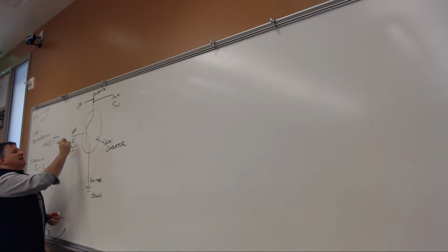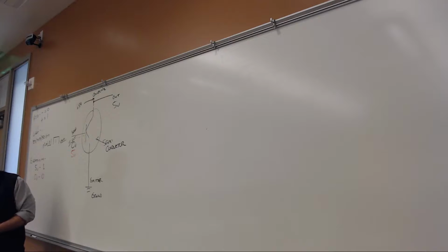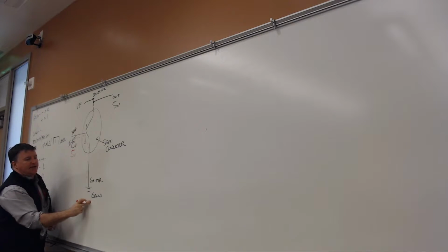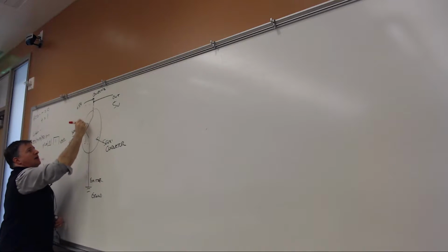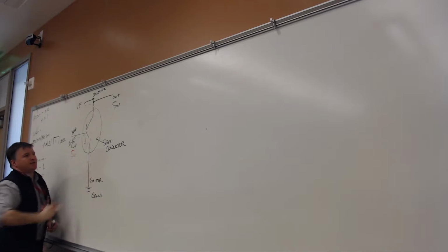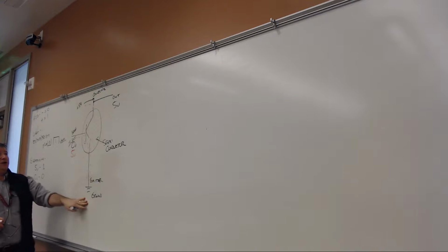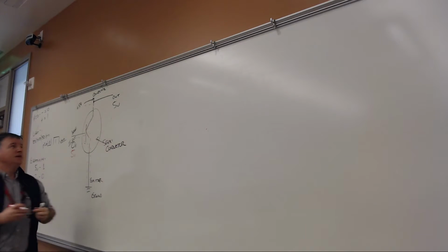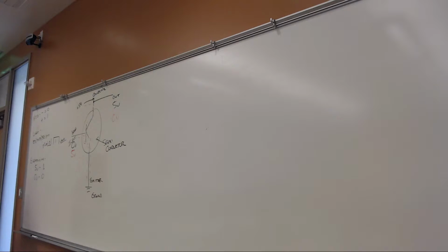And when it becomes a conductor, all 5 volts that I put in here, where does electricity like to go? To ground. So it all travels down to ground down here. The 5 volts that I have up here being applied to my collector all come down and go to ground. So if all 5 volts from here are going to ground, what's coming out? Nothing. 0 volts is coming out at that point in time. That is the basic properties of a transistor.